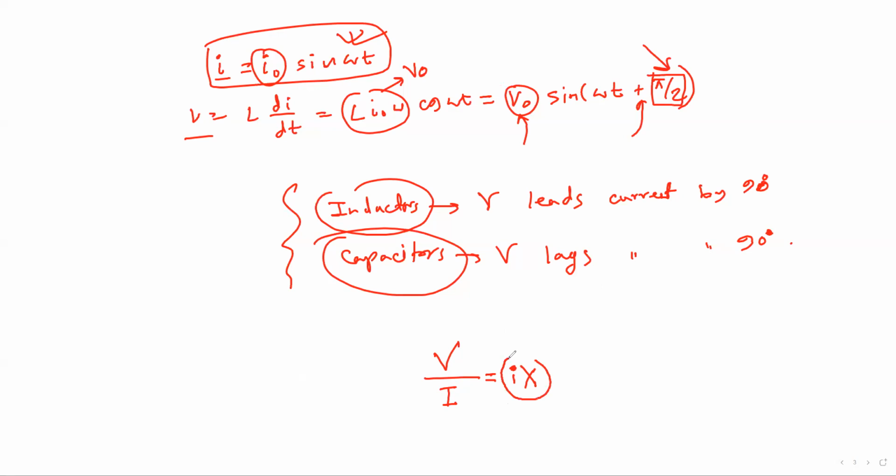If you express this current and voltage using complex numbers, then this makes perfect sense, because voltage is actually adding 90 degrees additional phase to current when you get the expression of voltage from current, right? So technically voltage is just some pure imaginary number times current, so that after multiplication the voltage is something that has 90 degrees more phase angle than current has.